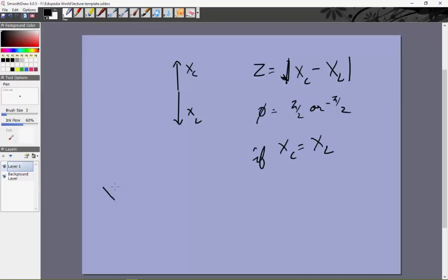So when you have XC equal to XL, then you have large current. We would say infinite current, but again there are many things which we have to consider when we go from an ideal case to a real case, such that there are no actual wires which have zero resistance. Even the attaching wires would have some resistance, so you would have to take care of that as well. But again, I really apologize, I'll make an effort to make my L's and C's look better. If this is true, then we have a large current, and that is called resonance.